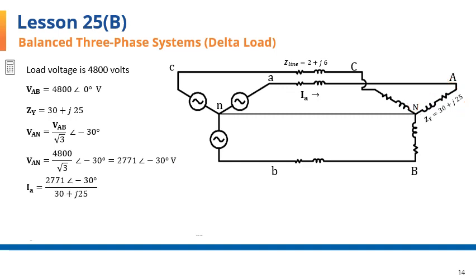And of course, the same current that goes through the phase is the current that is coming from the generator over the lines. So we're actually finding IA by dividing the voltage over the impedance of the load, and IA comes to 70.97 amperes with negative 69.88 degrees of phase angle. Subtracting 120 degrees from this phase angle will give us IB, calculated, shown here. And subtracting another 120 degrees from this one will give us IC, that's given here.